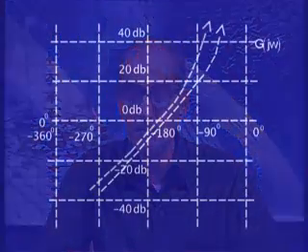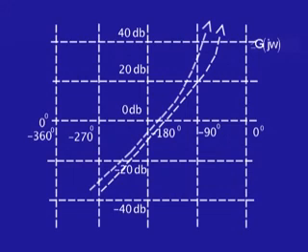The g j omega curve will simply shift. If I have a phase shift, the gain is the same at every point, but there is only a phase shift. So, if I know the compensating network phase shift, I can plot the new g j omega curve rather quickly. If there is also varying gain for the network, I can take care of that by moving up or down.